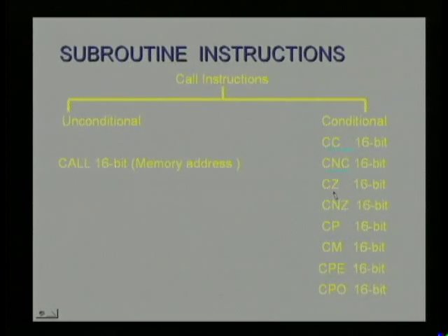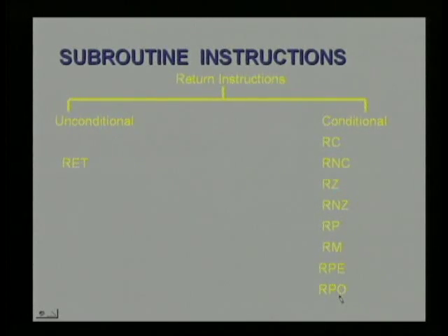This is the case with zero flag, that is call on zero, next call on no zero. With sign flag, call on plus and call on minus. Next with parity flag, call on parity even and call on parity odd. Now let us see return instructions.